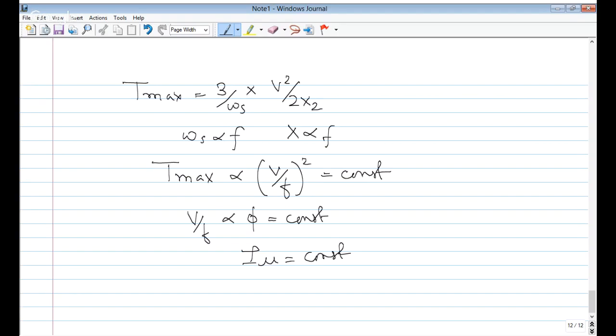The voltage stress will be maximum in an underground cable at the surface of the conductor. Remember this, in a conductor, the electric field or the stress is maximum at the surface. So inside the conductor, electric field is zero. So at the surface, it is maximum. Then it decreases hyperbolically. So this is at small r. This is at capital R. Here it will be Q by 4 pi epsilon naught R. That is the maximum electric field or electric stress.